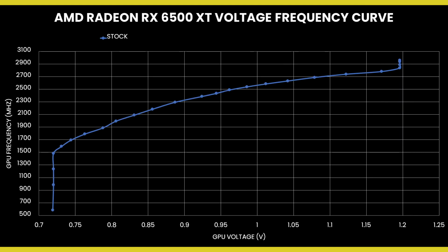The standard minimum GPU frequency is 500 MHz. By increasing this value, we essentially prevent the GPU from using the bottom part of the voltage frequency curve. In some benchmarks, this helps improve performance. However, increasing the minimum GPU frequency is not without its own challenges.